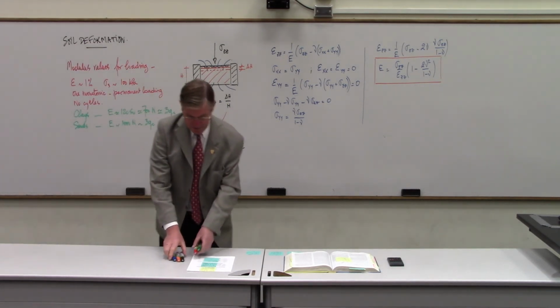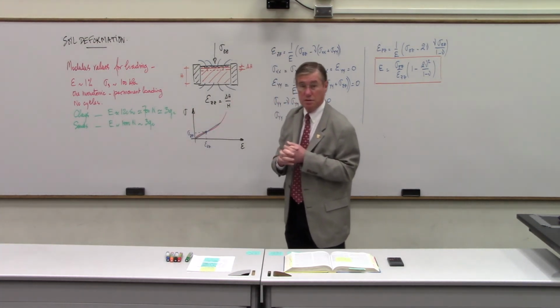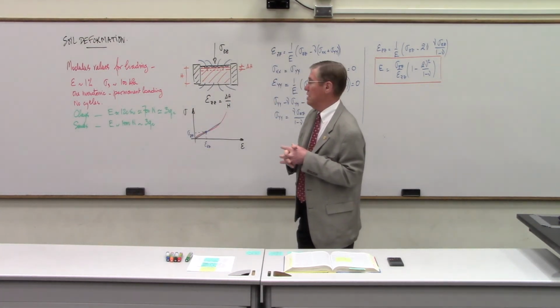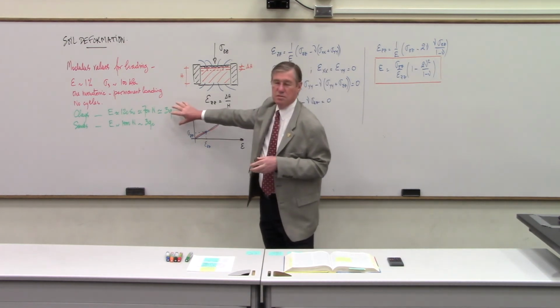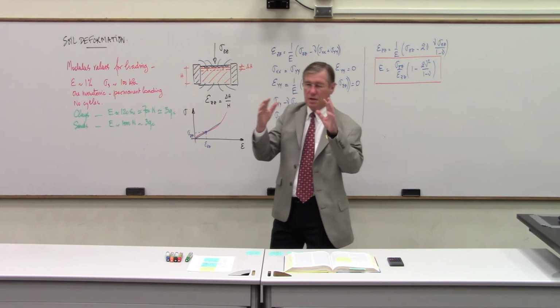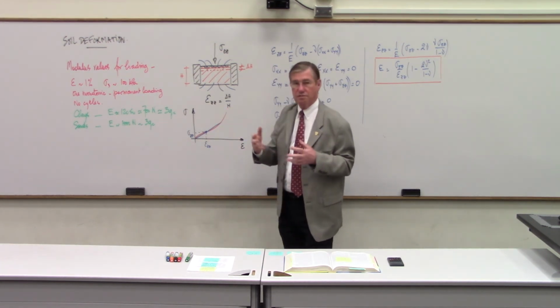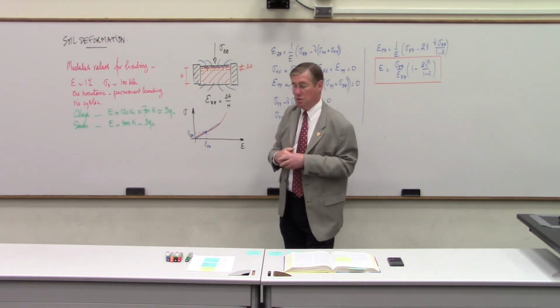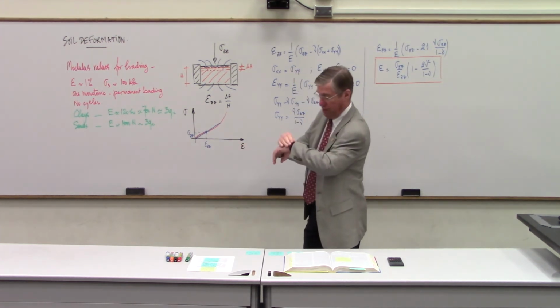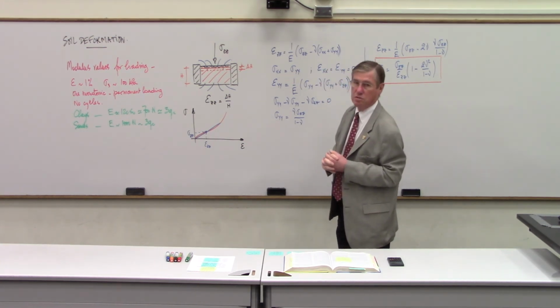So these are orders of magnitude. Considering the complexity of this number, the modulus of deformation of soils, these are only a first estimate. You're in the field, you say, okay, what kind of settlement can I expect? You can use some of those things to get a feel for it, but you must measure this particular parameter because it's very important to do so to have anything reasonable.